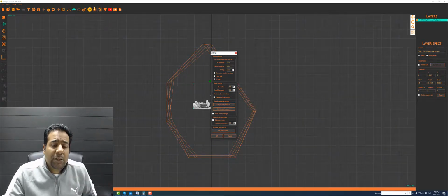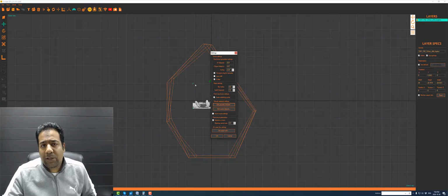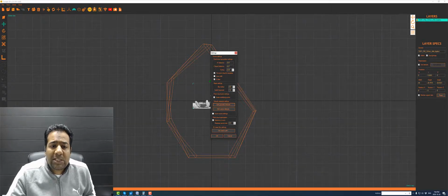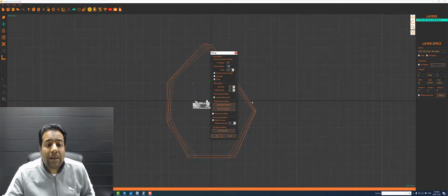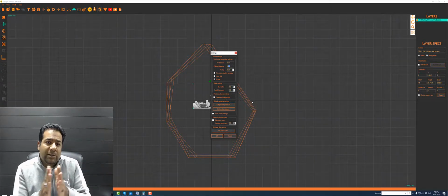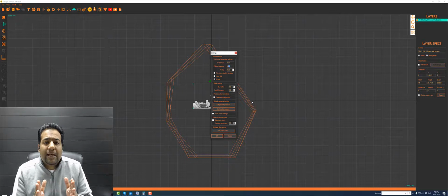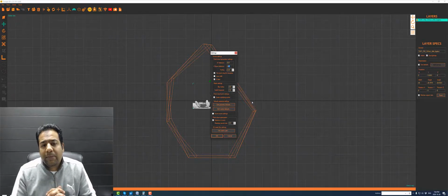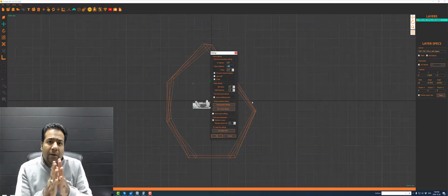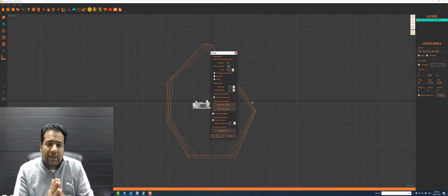Now, if your image is cracking, then what you should really do is reduce your power on your laser. But if that doesn't help, then in that scenario, you really have no choice but to start off by increasing the space on your Z axis from 0.07 maybe to 0.08, 0.09, 0.10. As you do that, it will spread the points between layers a little more on the Z axis, and when you do that, it will avoid or reduce the probability of cracking taking place or of those points melting together. So you can do that.